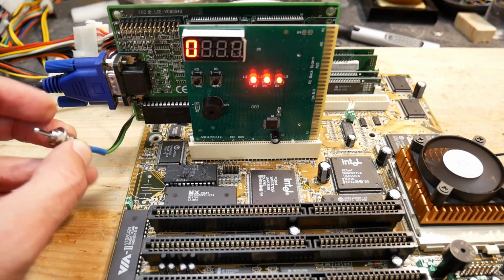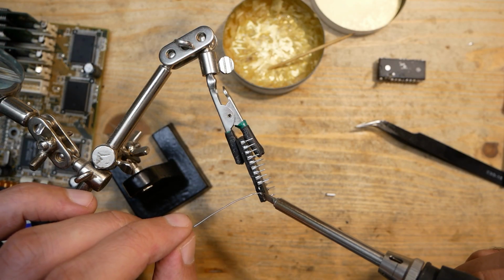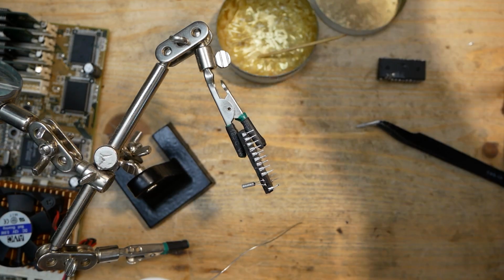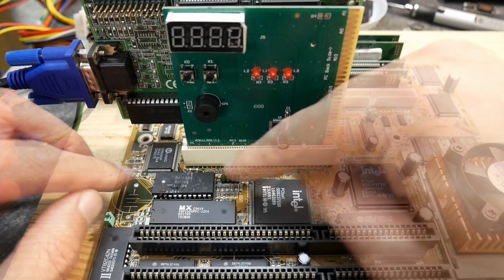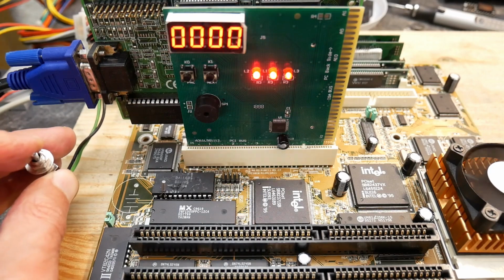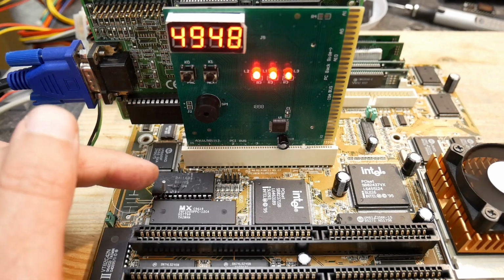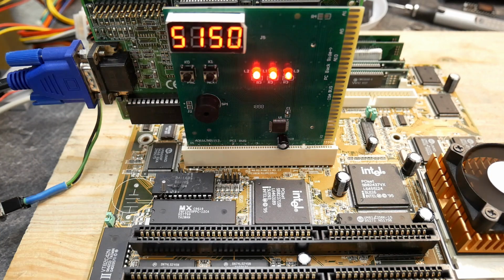That was kind of surprising to me, because it should run also without the crystal and the battery. I still can't explain the behavior, but as I soldered the crystal, which I got out from the same module, back to the broken-off pins 2 and 3, the system suddenly woke up. Maybe this was some kind of coincidence, maybe a bad contact in the socket or something else, I'm not sure.